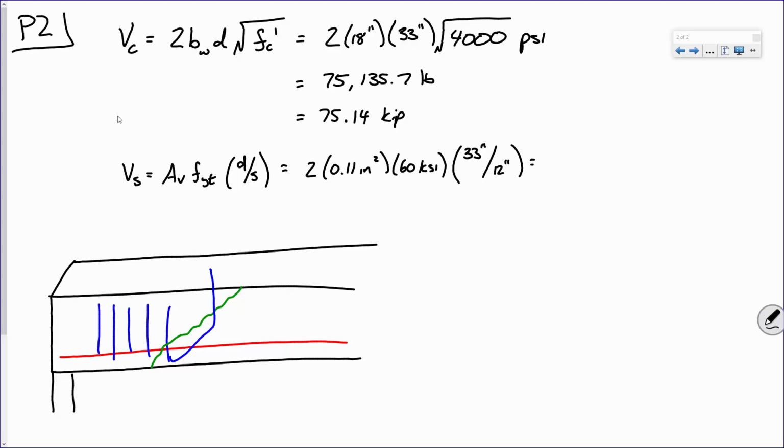And when we get that data, let's see if we can map a simple equation to that data. And what you find in concrete design is that the square root of f'c matches things quite well in a lot of cases. But because of units, when you put in psi, you get out psi. It's a little wonky, but it's something you gotta just pay attention to.